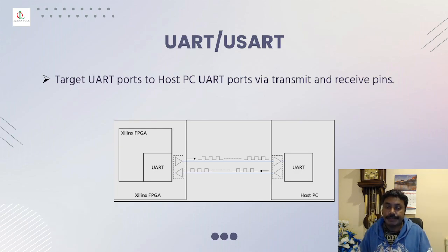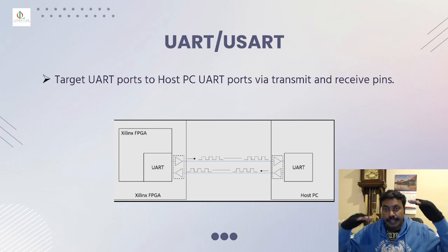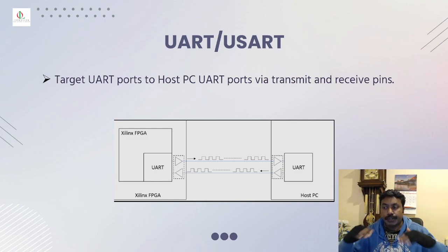There are plenty of baud rates out there, but the standard one most everyone uses is 9600. If you set this baud rate to 9600, then the other end has to be set as 9600. Otherwise there is no data communication, no transfer or receive happens, because you will get plenty of errors and you won't even start to send any form of data. So please make sure both sit on the same baud rate, nothing changes, maintain the same speed. That's what really counts.